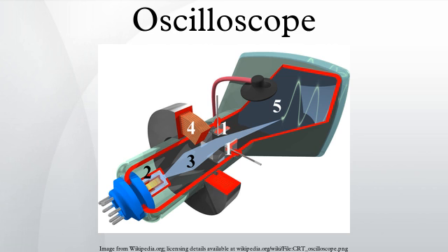Front panel controls. Focus control. This control adjusts CRT focus to obtain the sharpest, most detailed trace. In practice, focus needs to be adjusted slightly when observing quite different signals, which means that it needs to be an external control. Flat panel displays do not need focus adjustments and therefore do not include this control.